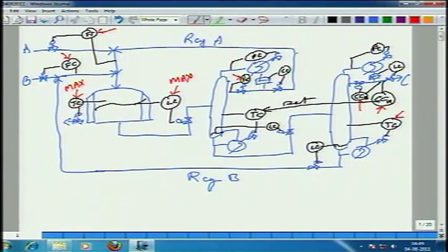C. You can't let too much C into the recycle A stream, because that C again degrades to something. So, whatever reflux is necessary to make sure that too much C is not leaking out the top, that much reflux you have to provide. So, there is a reasonable way of fixing the temperature set point here, and fixing the reflux there.